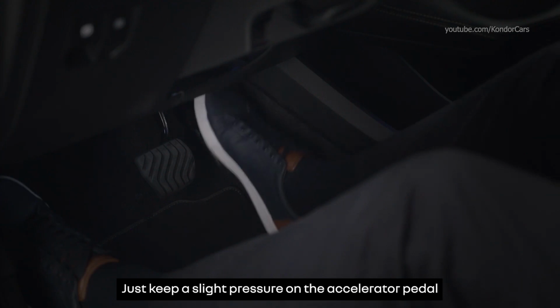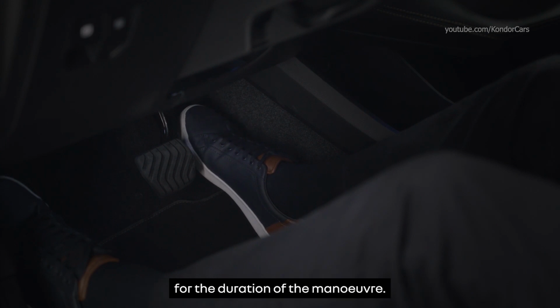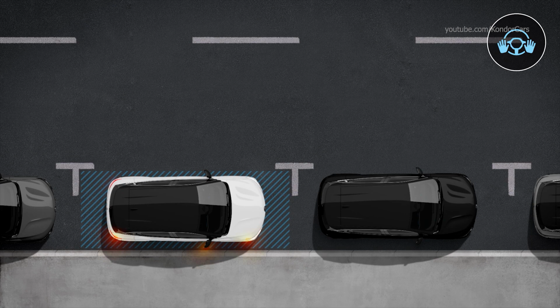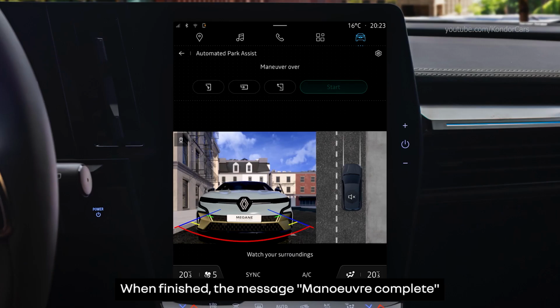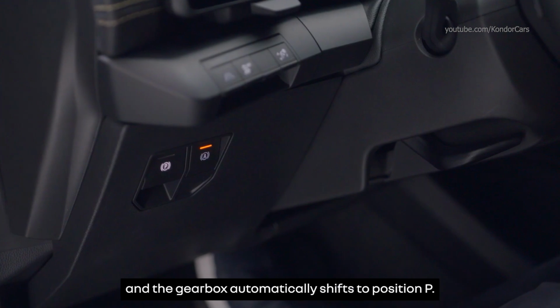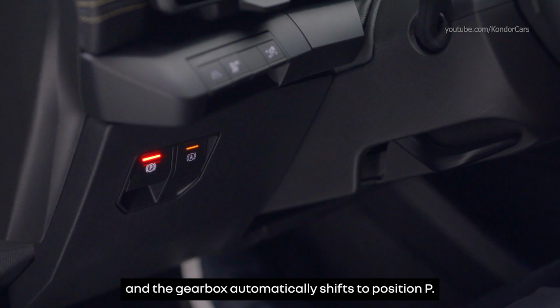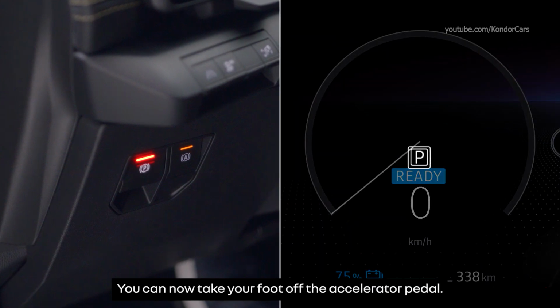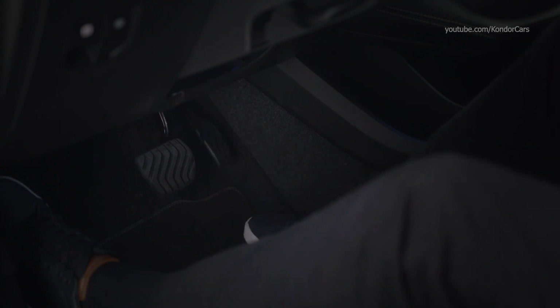Just keep a slight pressure on the accelerator pedal for the duration of the maneuver. When finished, the message "Maneuver Complete" appears on the screen. The parking brake is engaged and the gearbox automatically shifts to position P. You can now take your foot off the accelerator pedal.